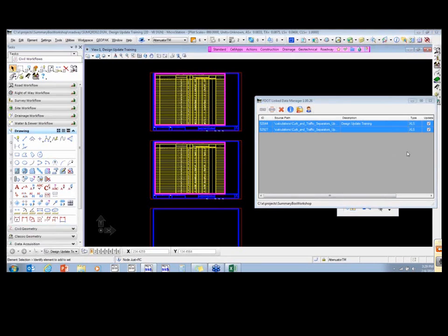Okay. From what he just read, the temporary crash cushion table summary box no longer goes in the temporary control plans, which is a different section of the roadway plan set. They go with the summary of quantities, behind the summary of temporary traffic control plan items.